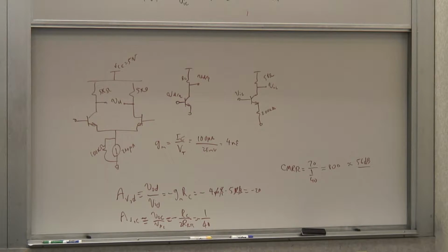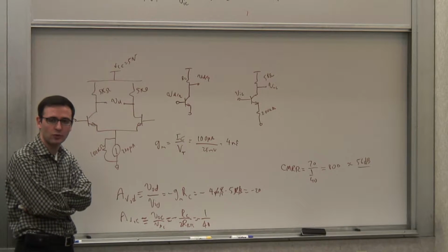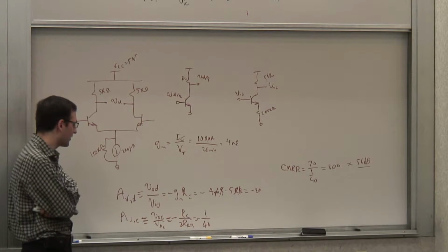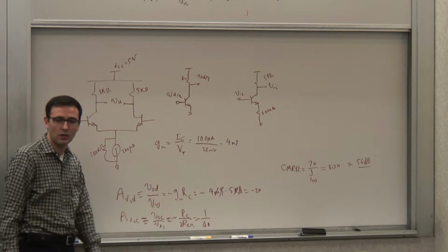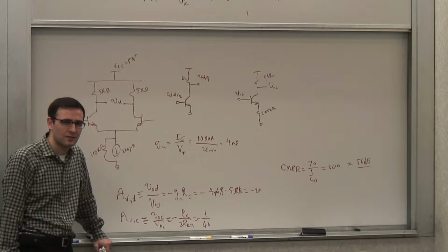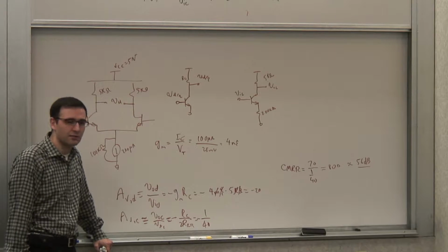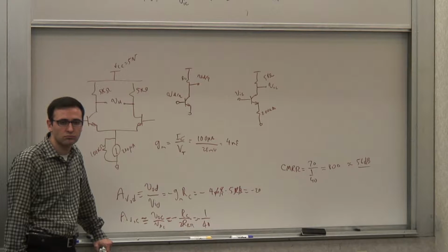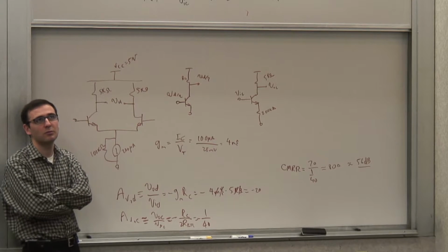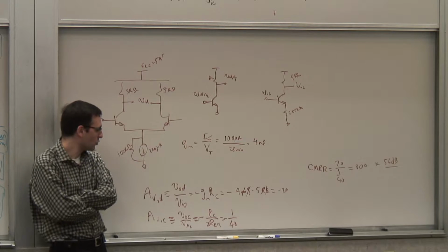Now, let's go back to your question actually. So let's say I want to somehow increase my input range. What do I do? You make RE higher and higher. Now, if I make RE higher and higher, would this be affected? We already talked about that. Sorry, RE would not help. You make RC lower. Okay, but that would lower my overall gain of this amplifier. So I can do that, but it doesn't make the range wider. Well, it would increase my input range. Yes, true. That's one way of doing it. So you could do that. You can make RC small.